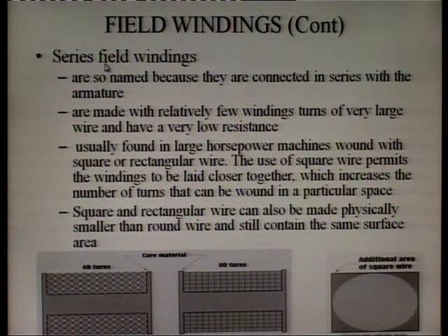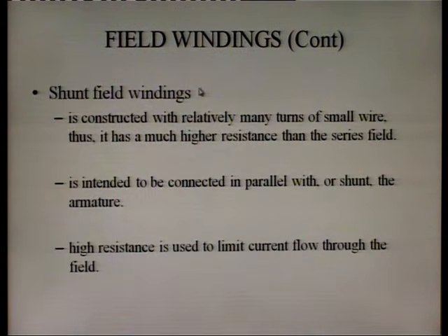So field windings are named series field windings because they are connected in series. As the field winding is connected in series with the armature, the resistance of the series field winding should be low, so that the voltage drop across the series field winding is minimal.